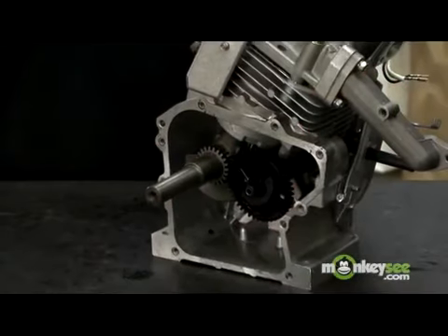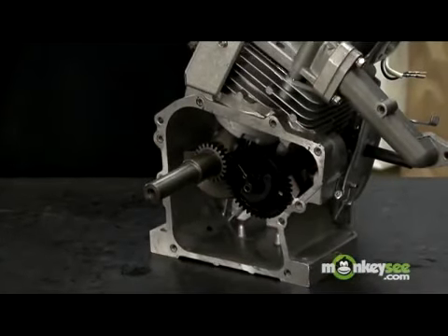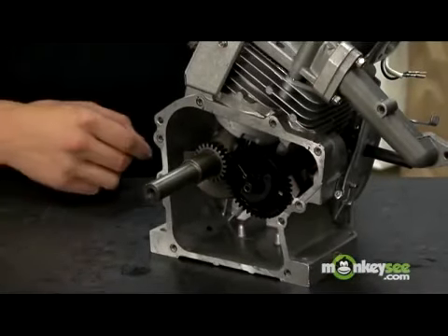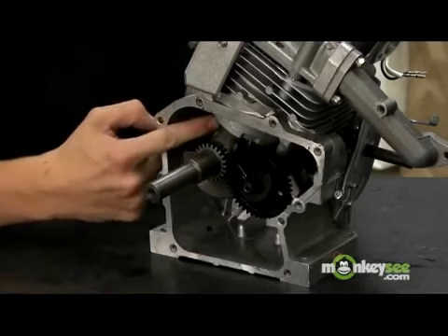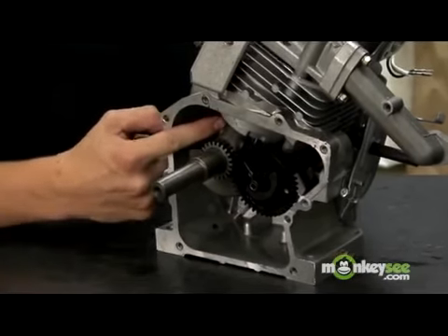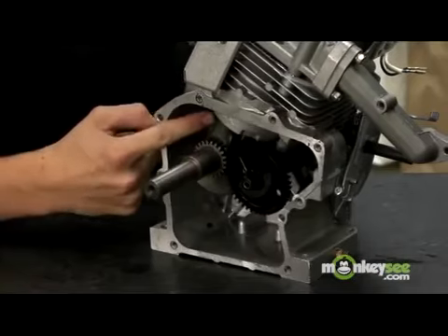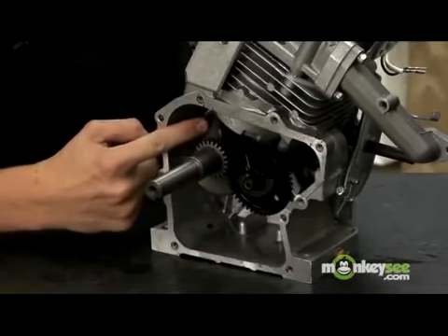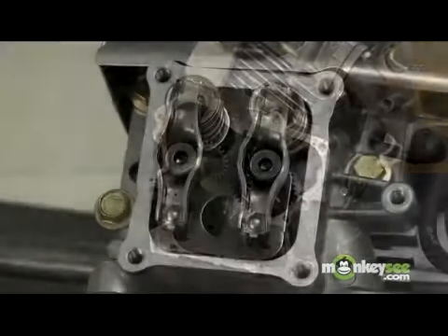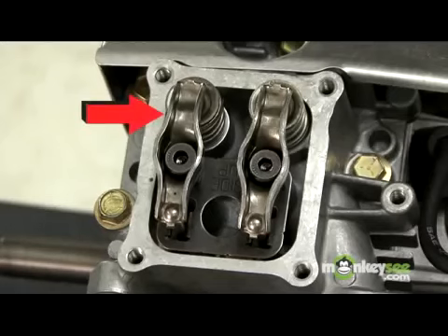To illustrate all of the components in the mechanical system working together, I'm going to start with the engine's first cycle. The piston is situated in its topmost point. The engine begins to rotate. The crankshaft pulls the piston down. The inlet valve is going to suck gas and air into the combustion chamber.